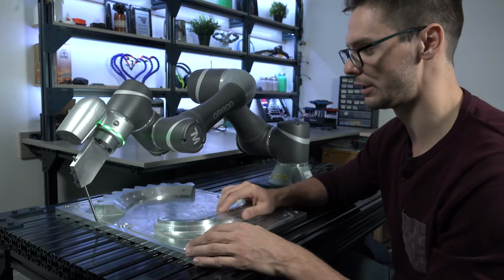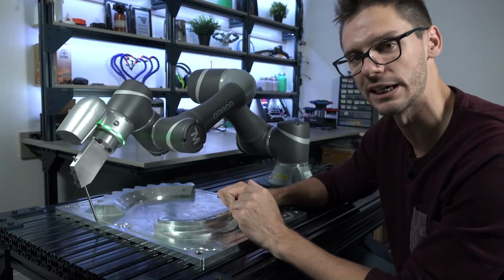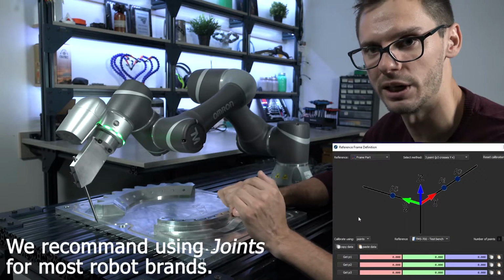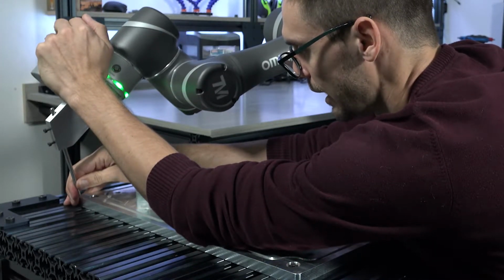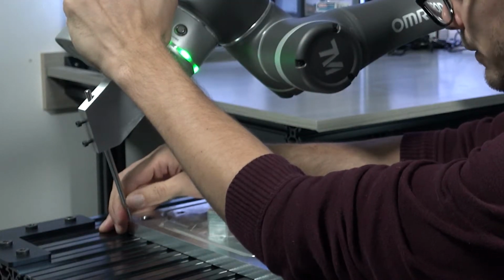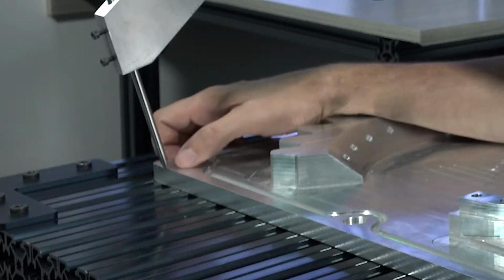Let's actually run the method. So first of all, for the exact same reasons as we've used the pose instead of the joints for the TCP calibration, we'll switch the drop-down menu to pose, and then I will bring my robot as close as I can from the origin and directly on the edge of the part here. Obviously I'm just driving it in free drive right now, so I can't really have a super good accuracy because I'm doing that manually.